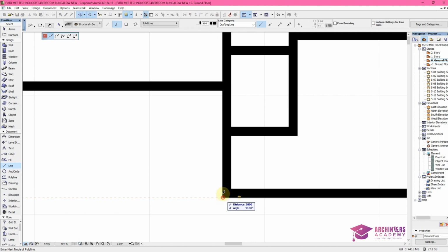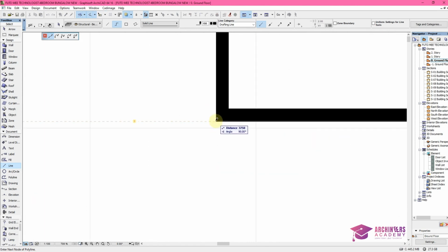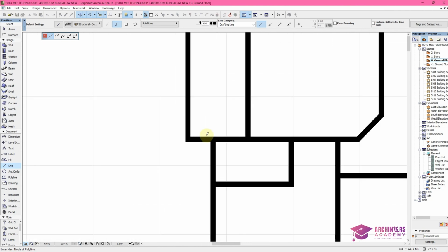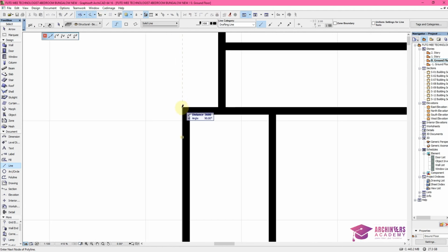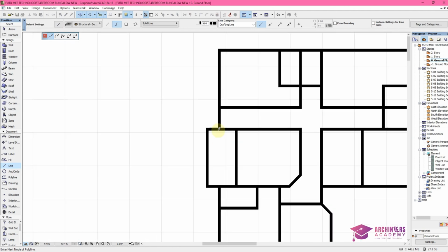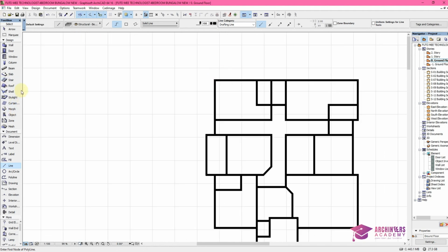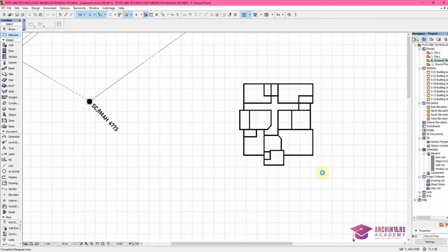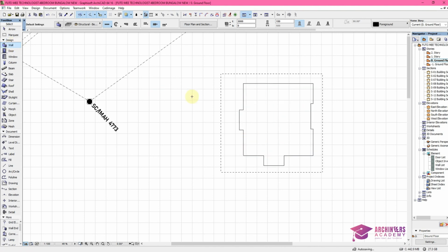For my boundary line, which is the one we use to draw the survey plan, we make use of 1.5 thickness pen weight. So right now I'm making use of 3.0 pen weight. I'm done redrawing the shape of the line. So I'll go back to marquee to just only delete the wall. I'll click on wall, Ctrl A and delete. So I've gotten the shape of my building.